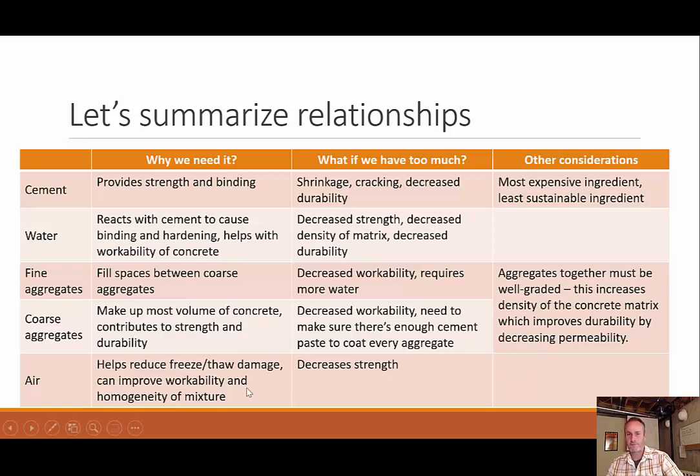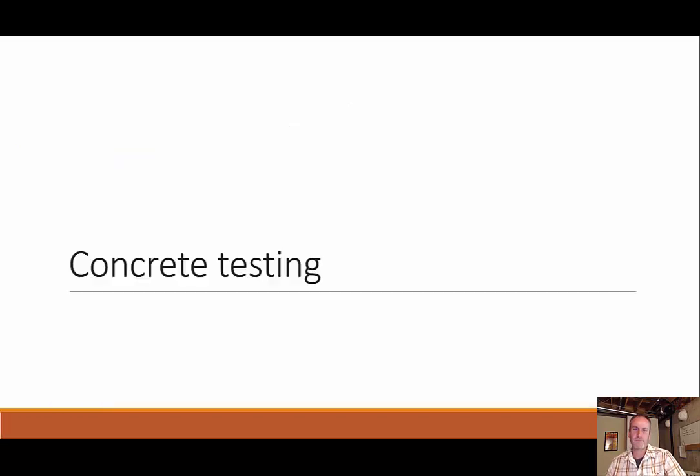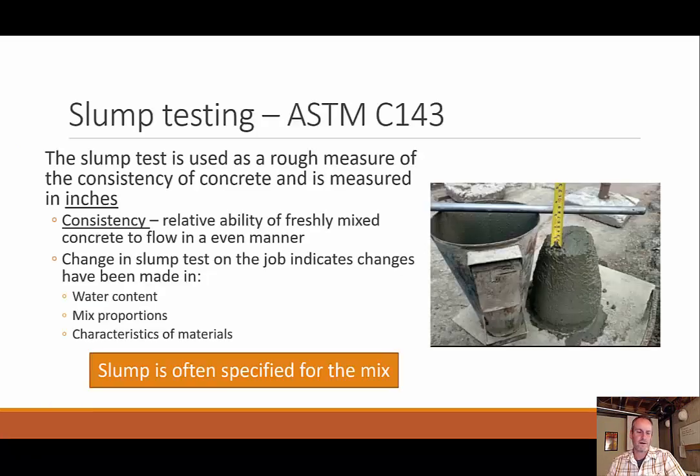Air, we said the purpose of air is it'll help reduce freeze thaw damage when you're in those conditions where the temperature drops. And it can improve workability. However, the more air we add, the less strength we have in our concrete. So let's move on to testing our concrete.